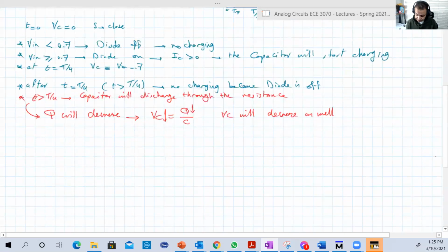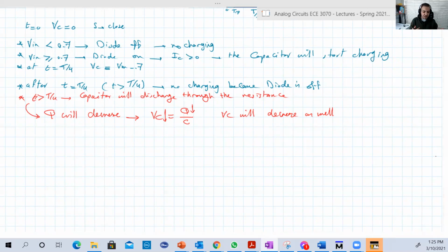And that's not good. Yes, that's really not good. Because when we don't have a load, the load is infinity, the voltage becomes constant, just DC. But now, no, it will decrease. So let's study this decay in voltage, or this decrease in voltage, and its relation to time, the capacitance and the load resistance. And let's see if we can control it somehow so it will not decrease so much.